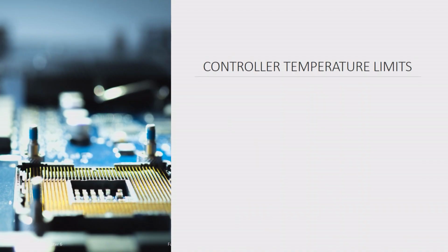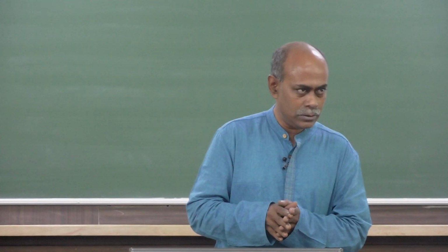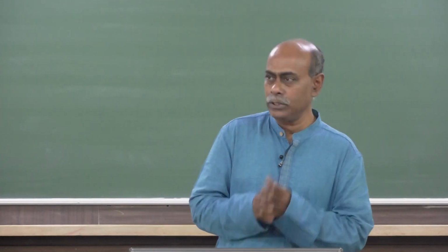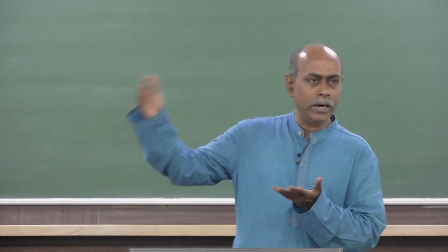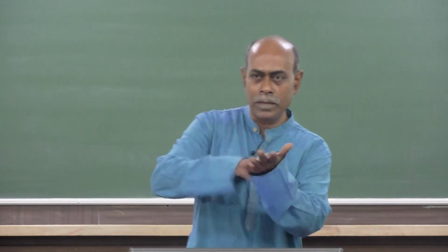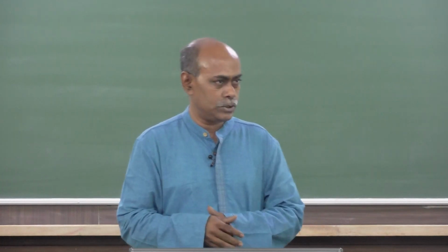So, the idea of this lecture is to give you a quick overview of the important thermal considerations in electronic design, in particular in power electronic design, because that is where thermal becomes a significant challenge, and how to address them. And these have to be done at the design stage when the circuit layout is being designed, when the components are being selected. It is not an add-on that after you finish all the design you slap on a fin and then put a fan and keep it cool, it is not like that.